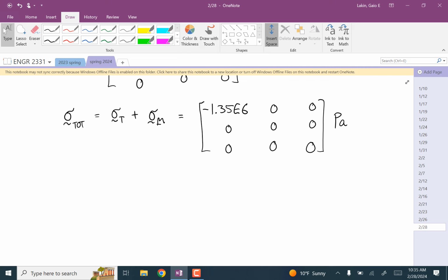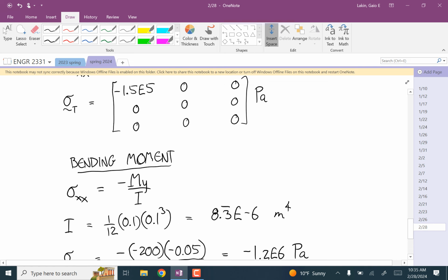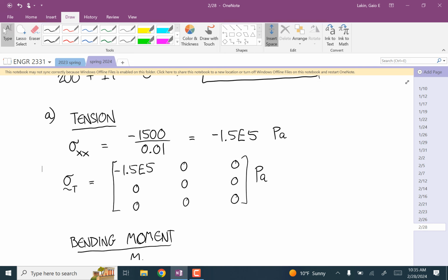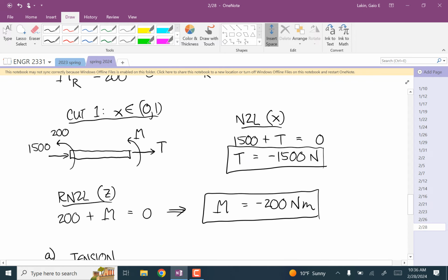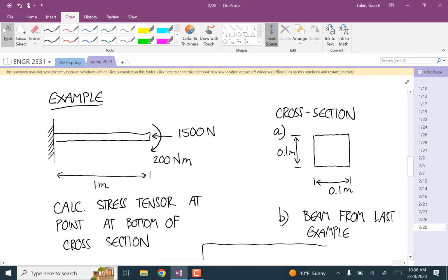Yeah? Sorry, for the area moment of inertia, how do you determine what is the base and which is the height? The base is along Z, it's horizontal, and the height is, yeah. Thank you. And so it makes sense if you think, okay, the one that's cubed in the formula is the one that, remember this example, in order for this to be the strongest, you want it really tall, and that's the one that you're cubing, the height. Yep.